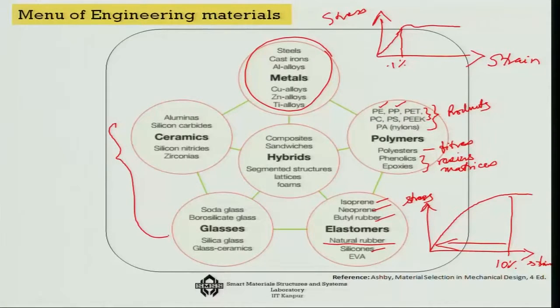if it falls down, it breaks into pieces, and the same thing happens for ceramic pots. So, ceramics and glasses share a very common property, that both of them are very brittle in nature, but even though they are brittle, their basic microstructures are actually different. For ceramics, as I told you, you will get a very regular atomic structure, crystal structure. On the other hand, in glasses you will not get a regular crystal structure. So, in the ceramics, there is this group of alumina, which, I told you, is used mostly in making fibers, or in refractory bricks.